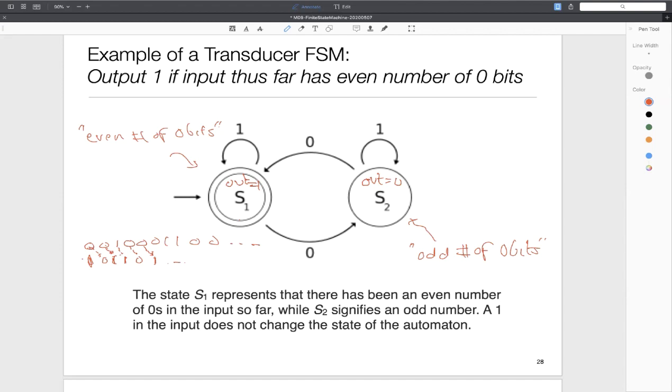So if you think about what the underlying combinational logic would look like, it will only examine the contents of the state register and then compute output from that. So to calculate the output, I only need to know the state I am in. Okay, I see. Thank you. Whereas in some examples, you might see that to compute the output, I not only have to look at which state I am in, but also what input currently is there. Okay, so that's why.